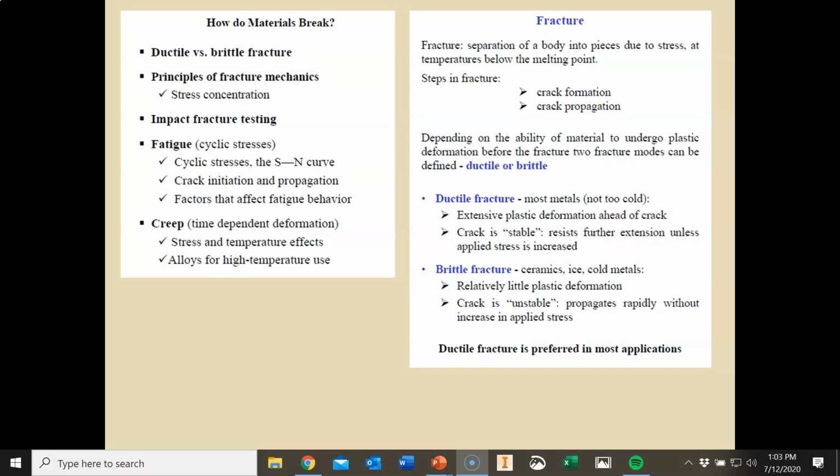This perpendicular fracture leaves a relatively flat surface at the break. Besides having a nearly flat fracture surface, brittle materials usually contain a pattern on their fracture surfaces. Some brittle materials have lines and ridges beginning at the origin of the crack and spreading out across the cracked surface. Since there is very little plastic deformation before failure occurs, in most cases this is the worst type of fracture because the visible damage cannot be repaired in a part or a structure before it breaks.